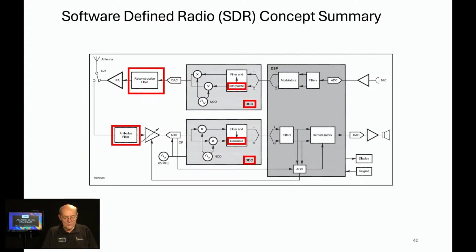So we're going to have a couple of phases in this discussion. We'll show the concepts, and then we'll dig into a little bit more. Generally speaking, the DSP circuitry quite often can't run at carrier frequencies, so we have to do some down conversion. In my 7610, for example, most of the DSP happens at 2 megahertz, even though it is directly converted to digital right at the antenna. To do that, we have what are called down converters and up converters, receive and transmit.